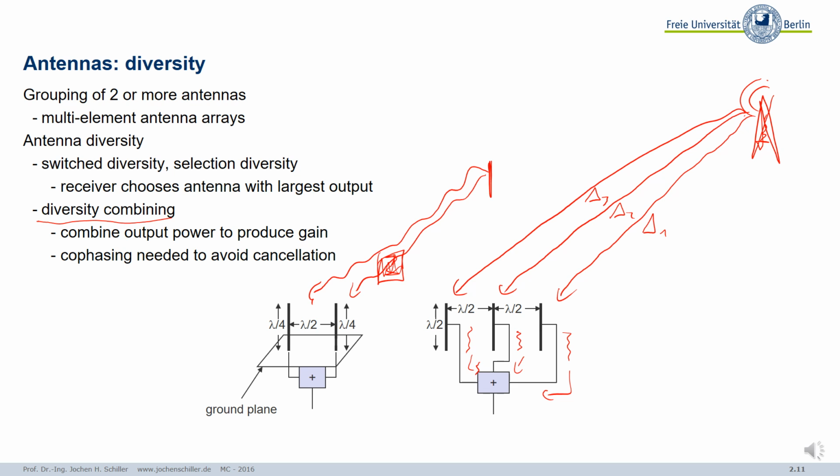Even in this situation, you see that delta 3 is larger than delta 2, is larger than delta 1. Why? Because we have a limited speed of light. And now assume 30 centimeters is 1 nanosecond, which is only true in vacuum. We don't live in vacuum, but okay, let's assume 30 centimeters, 1 nanosecond.